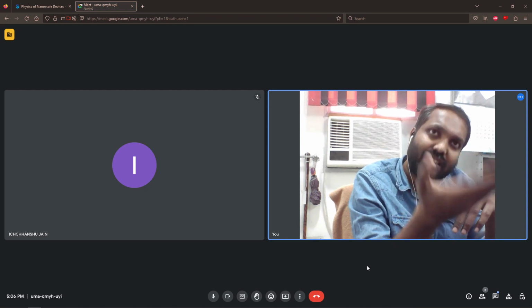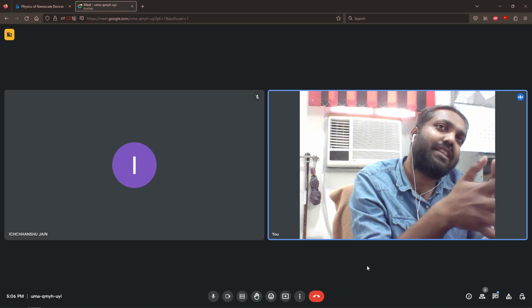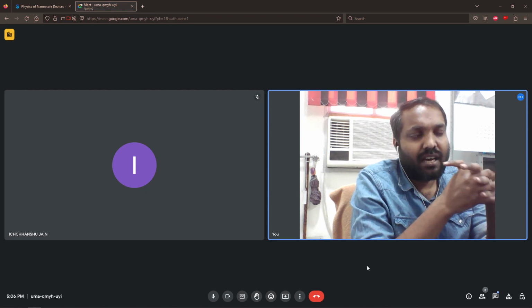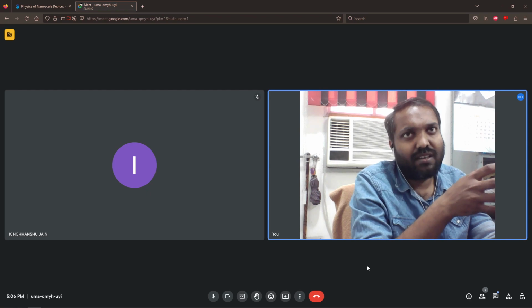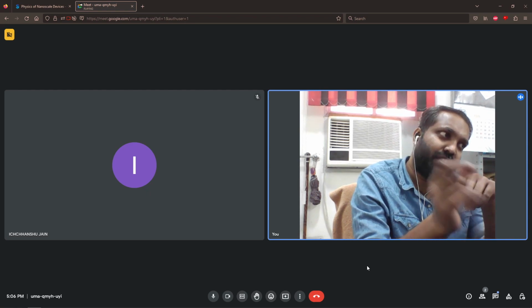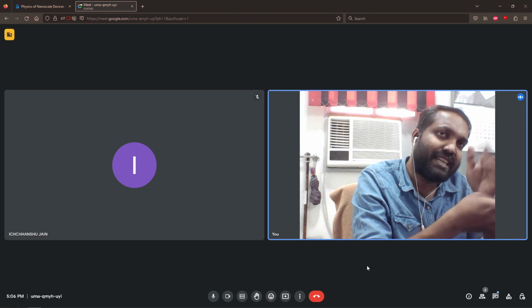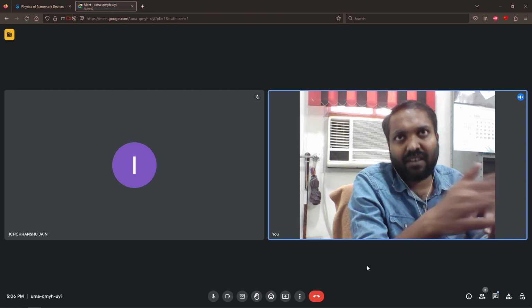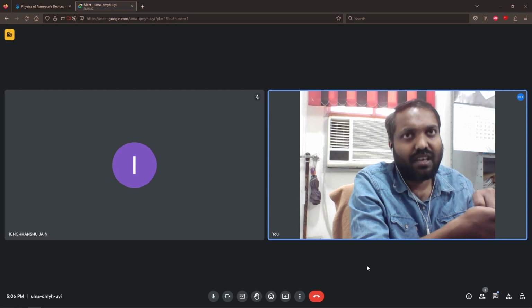By dividing the current flowing through the channel by the charge stored in the channel, we get the notion of the average velocity, or what is known as the average ballistic velocity of the electron. And by using the previously defined concept of the zero electric field point, we identify this velocity as the ballistic injection velocity into the channel. And the Fermi integral ratios for that was also seen in today's discussion.